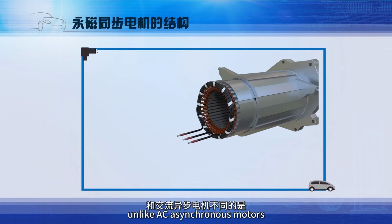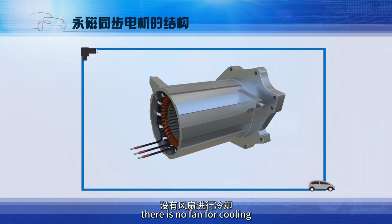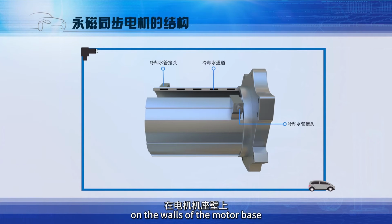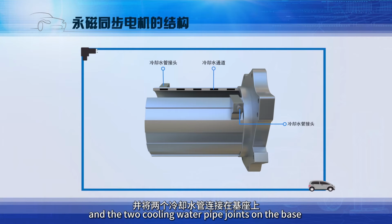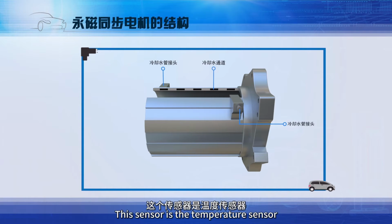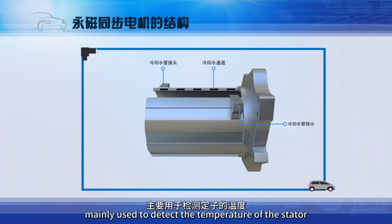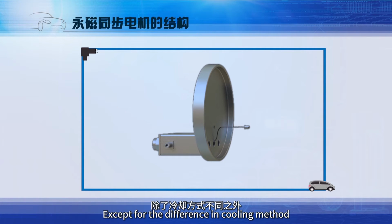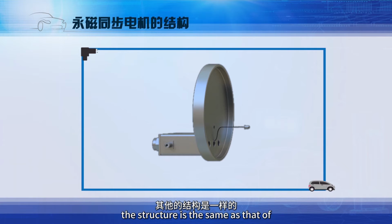You may notice that unlike AC asynchronous motors, there is no fan for cooling. Yes, permanent magnet synchronous motors mainly use water cooling. There are cooling water channels on the walls of the motor base, and the two cooling water pipe joints on the base are the inlet and outlet of the cooling water. This sensor is the temperature sensor, mainly used to detect the temperature of the stator. That's all for the stator part. Except for the difference in cooling method, the structure is the same as that of AC asynchronous motors.